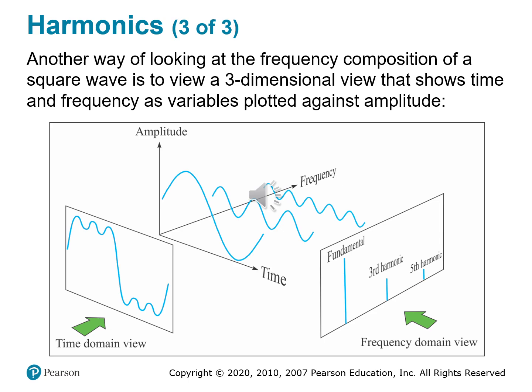So let's look at the time domain view. This is a familiar plot, amplitude versus time. You see the waveform as it unfolds in real time. And so for the square wave here, we see ripples from the added harmonics. And we call that the Gibbs phenomenon.